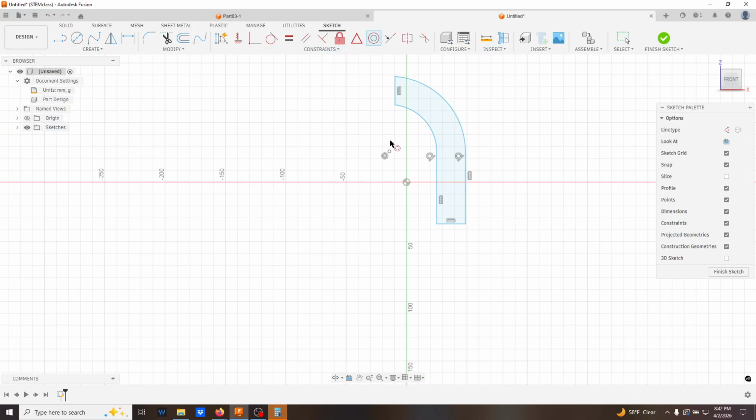So it's kind of interesting because making these two arcs concentric versus making their two centers coincident are different constraints, same kind of effect, but you can really take advantage of that, especially when it comes to dealing with circular edges, because sometimes the math gets weird. So I'm going to finish this off by putting this coincident with that, and then boom, I have my general shape.